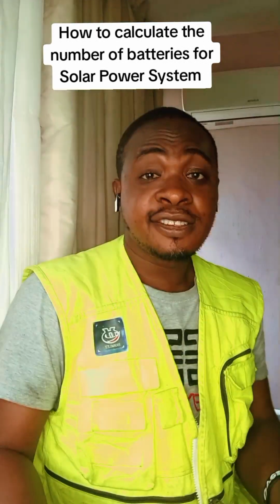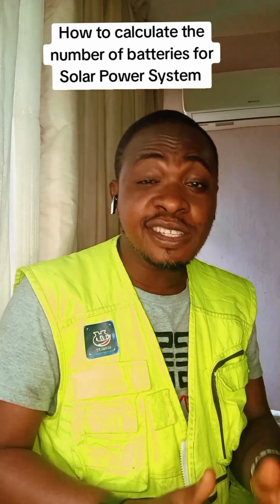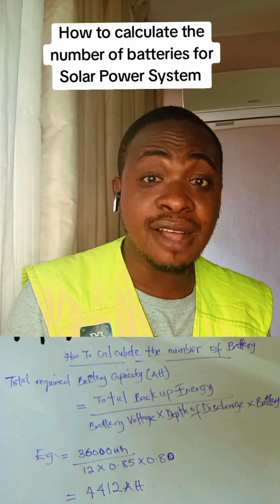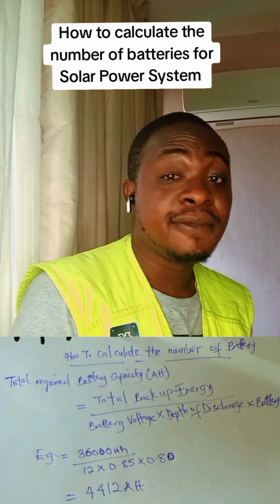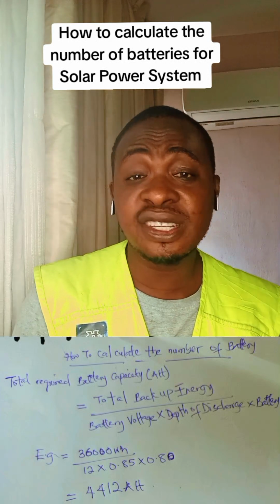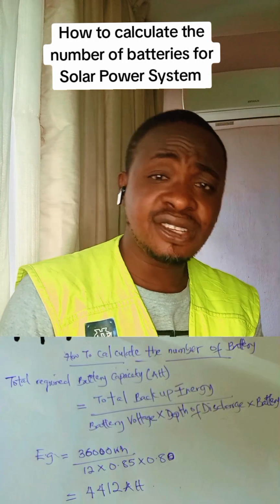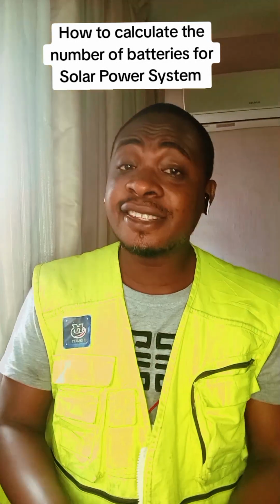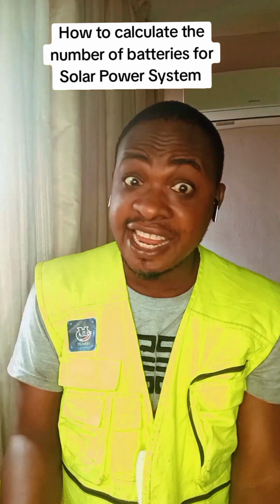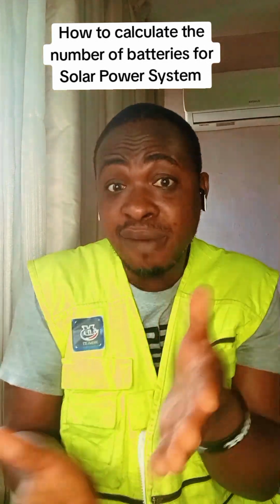Do you get it? So from the example we calculated earlier, the total backup energy is 36,000 watt hours. We're going to divide it by the battery voltage, which is 12, then the battery efficiency, which is 0.85, then divided by the depth of discharge of the battery. That is going to give us the total required battery capacity for the day, which is in amp hours. Now the number of batteries, that total number